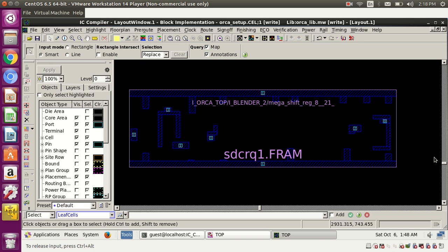So here the skew is more, then what are the fixes? We'll somehow do macro modeling or deleting the buffers, based on the previous discussion, I think you guys know. I think you understood the question now. The question is: our design is failing because of skew, and how do you analyze that? If you have understood the question, you know the answer, that's it. That's a simple question.